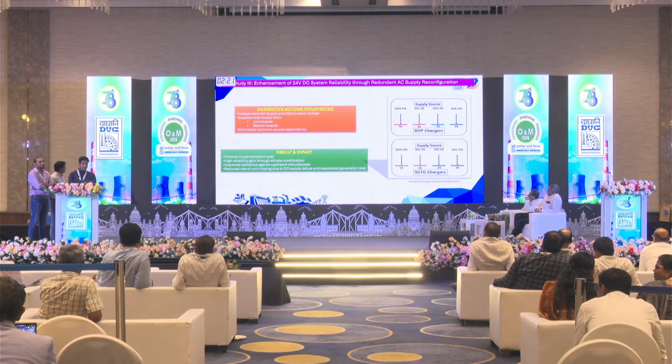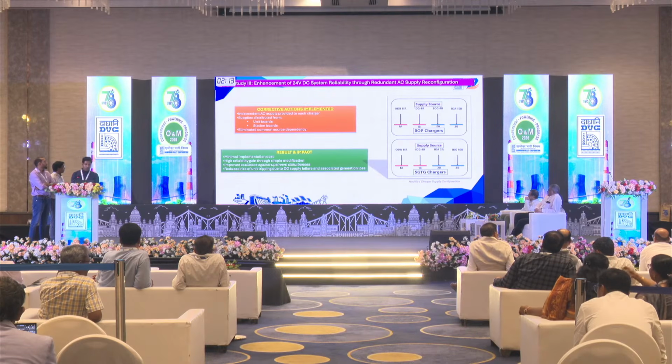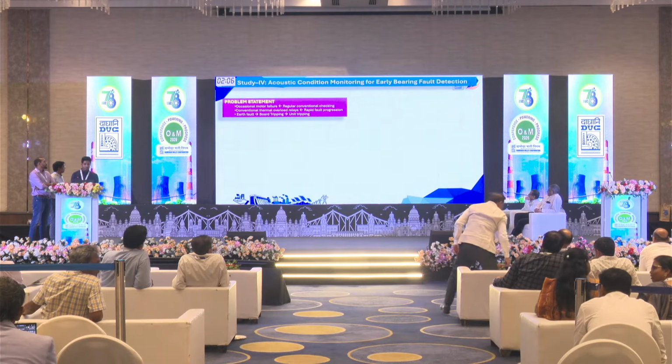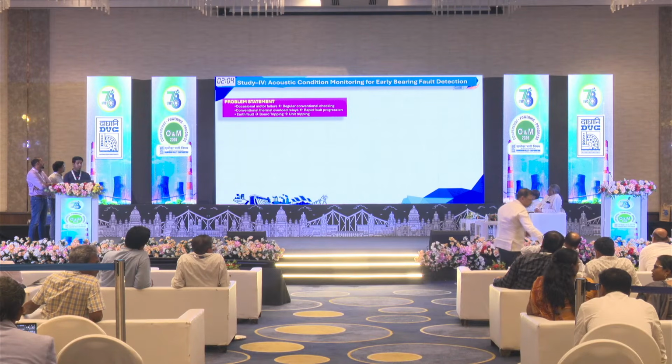With that, we gained high system reliability with a simple modification that involved minimum implementation cost because it only needed the cost of the cables. And we also made our system resilient against any upstream AC disturbances, thus reducing the unit tripping risk also. The last case is about acoustic condition monitoring.